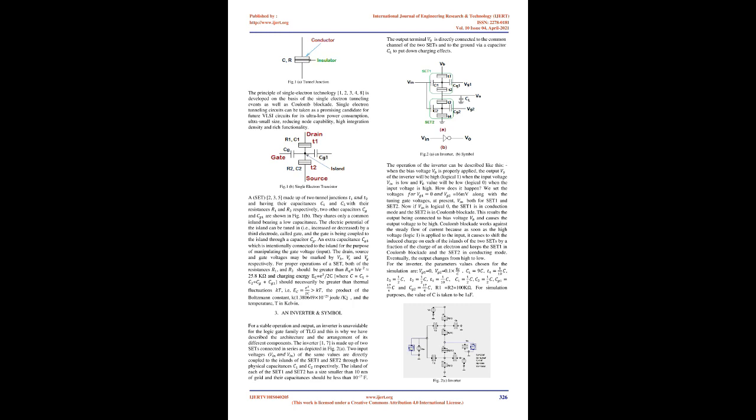We have the knowledge that current can't flow through the insulating barrier, as it creates a barrier against the movement of an electron in the case of classical electrodynamics, whereas for quantum mechanics, there must be a positive probability that an electron residing on one side of the insulating barrier, in order to reach the other side, can go to the other electrode when bias or input voltages are supplied. If a bias voltage greater than the threshold voltage is applied properly, there will be a current flow. Avoiding other effects, the current will flow in proportion to the bias voltage applied, as per the first order approximation of the tunneling process. In electrical terms, a tunnel junction, of course, has a constant resistance R value relying on its barrier thickness, as shown in Fig 1a.